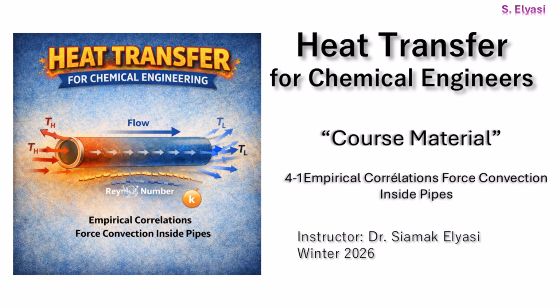Finally, for laminar flow, we switch over to different relations designed for that calmer regime. In these equations, you'll often see the Peclet number pop up, which is pretty simple. It's just the Reynolds number times the Prandtl number, and it's essential for modeling that smoother flow. So, these foundational empirical correlations provide crucial, practical tools for solving real-world heat transfer problems. Let's dive into more detail.